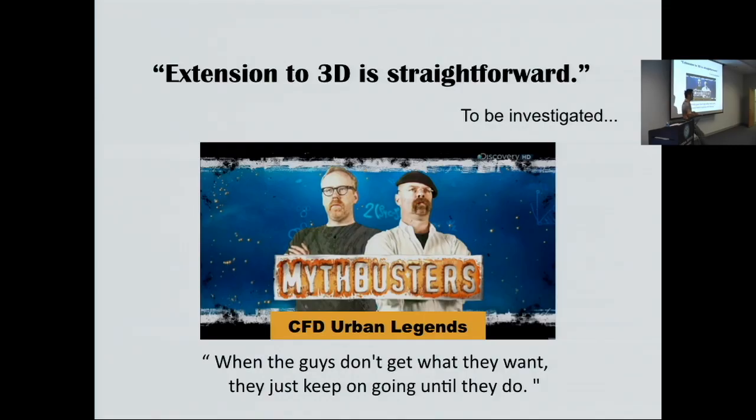Boris and Jim, you found that when you have highly stretched grids over curved surfaces, the least squares breaks down. And because this is using least squares, is that going to cause a problem when you have a large gamma? Because now your reconstruction is failing in the near distance. Even though you've got these accurate gradients, your reconstruction itself that you're using to get the higher order scheme is failing. Yeah, you're talking about high gamma, so it's not exactly in the limit of small mesh size.